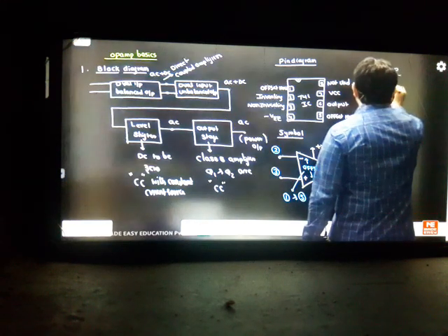So after completing the symbol, we have one more, the equivalent model, how to write. Can you see the amplifier equivalent model handwriting? Is there any difference between our BJT and op amps? You can see the difference. In op amps, they have designed in such a manner that the input impedance is infinite and the output impedance is equal to 0. They prepared op amps like this.